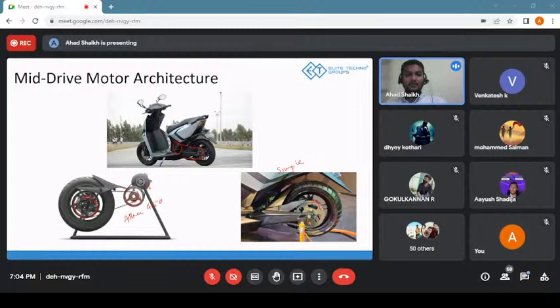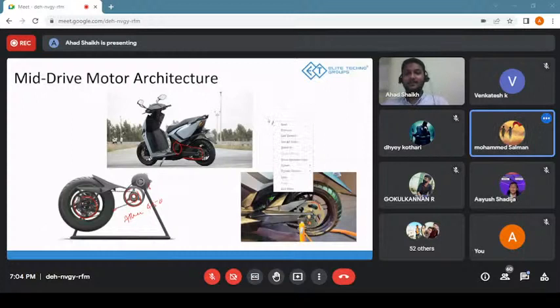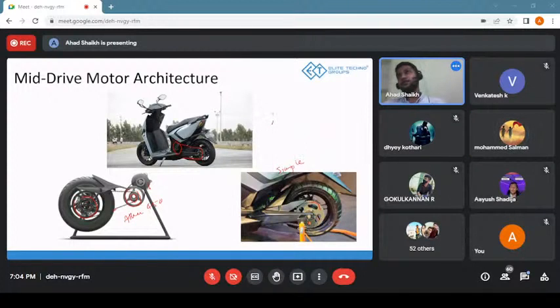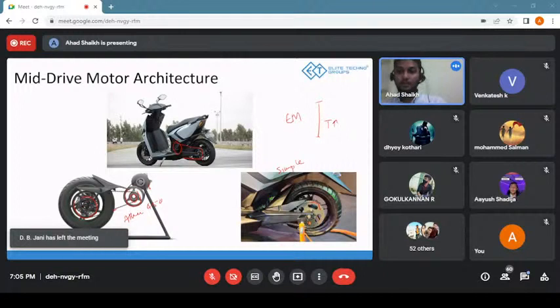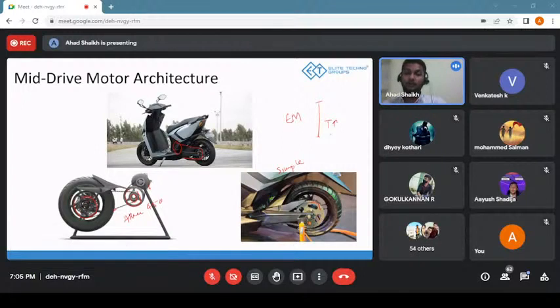What is the difference of having CVT, sir? Continuously variable transmission. Yeah, CVT could be used in IC engine applications, as well as manual transmission and automatic transmission. Yeah, great. So those are in terms of four-wheelers, but in two-wheelers you cannot have heavy gears and all such things. Yes, sir. When you already have an electric motor, it covers a long range of RPM, so you don't need a gearing mechanism. And one advantage it comes with is that it gives very high initial torque, so there also you don't need a high-torque first gear and all such things.